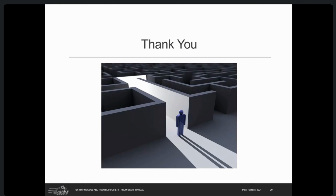I didn't put in the recording business, but when you get to your sensing point and you have a look and say, oh, there are these walls here, then when you add the wall information to the maze, you set a bit in the open maze for a wall present, and you clear a bit in the closed maze for a wall absent, right?